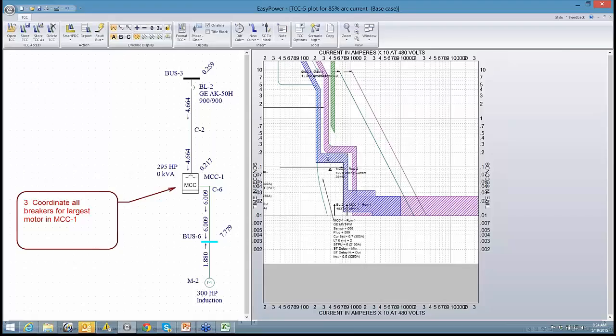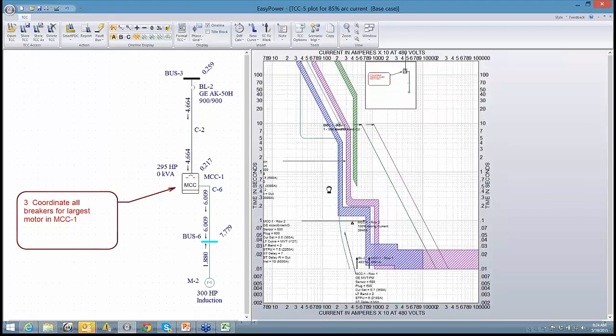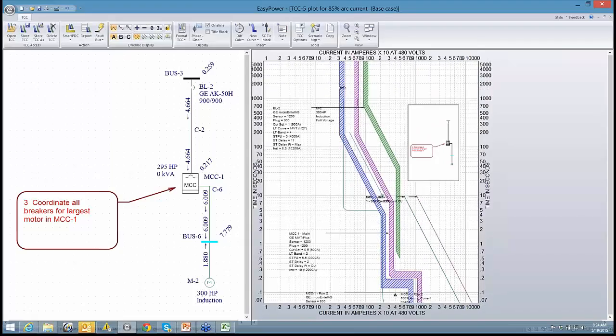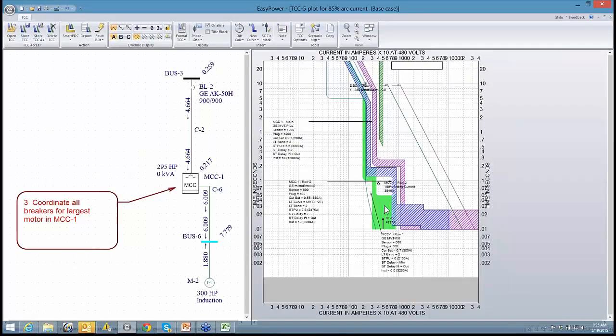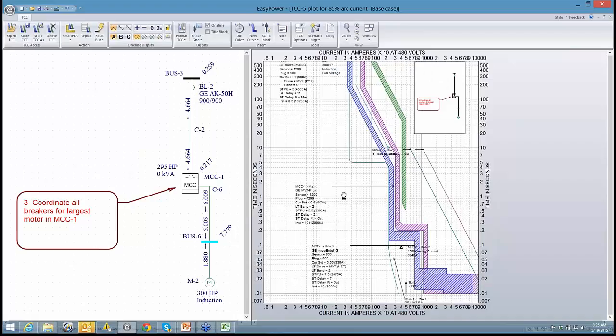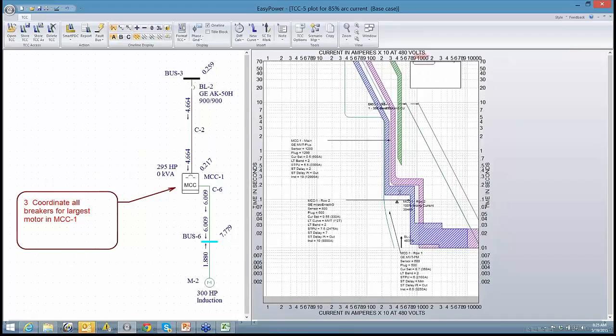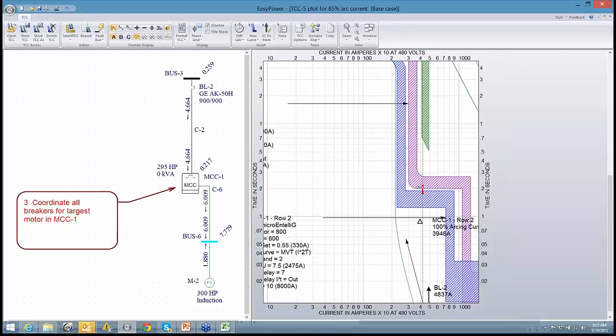I also want to move this set point a little bit to the right of this curve, and it keeps recalculating my arc current. Once all this is said and done, I want a difference between these two curves and to calculate that difference. And then my third curve, we'll set this up over the voltage fault current, the arc current.